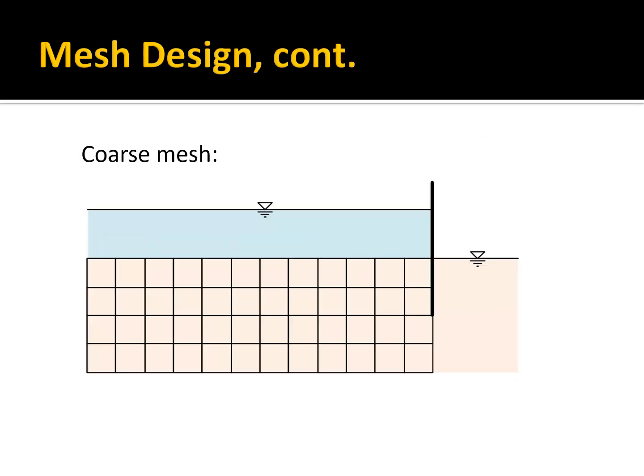If we're just looking at one side, you could theoretically use a set of coarse elements. We call this a coarse mesh because for the problem domain, that's not very many elements. In this case, the problem domain is rectangular, and so using quadrilateral elements works really well. Very easy to set up.